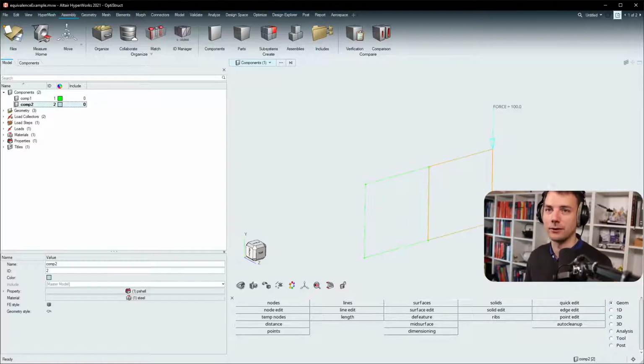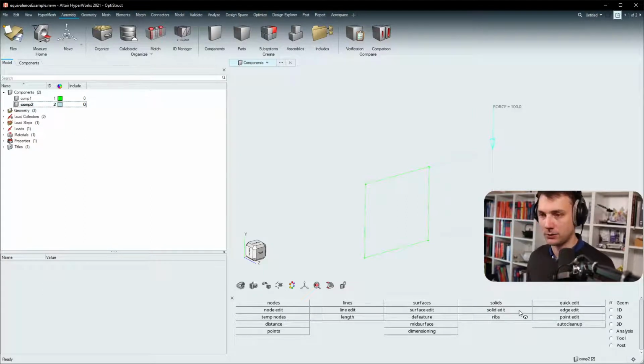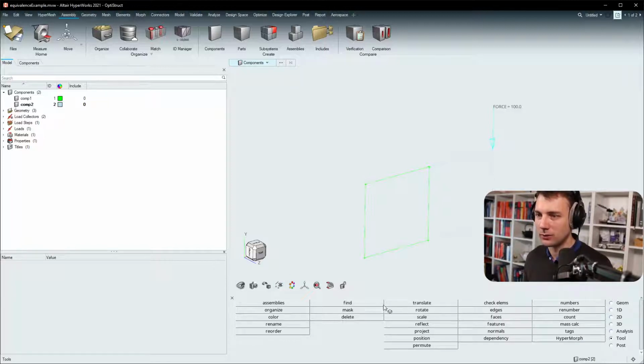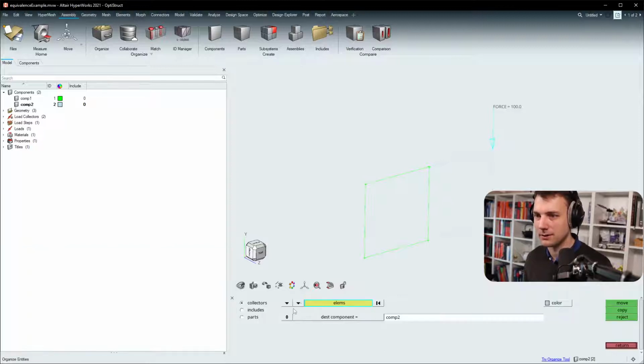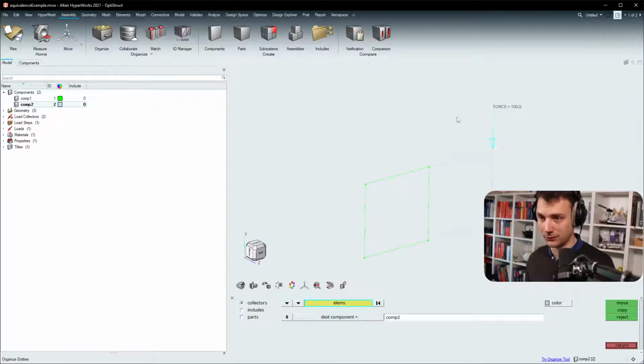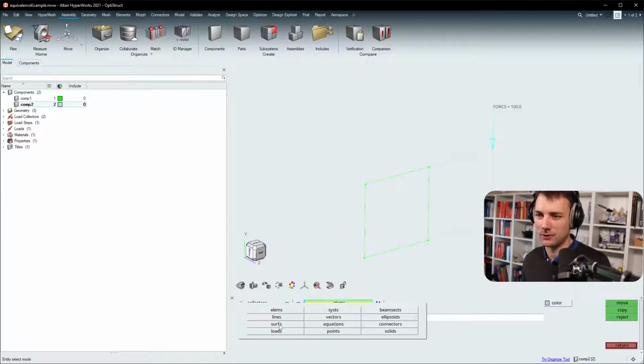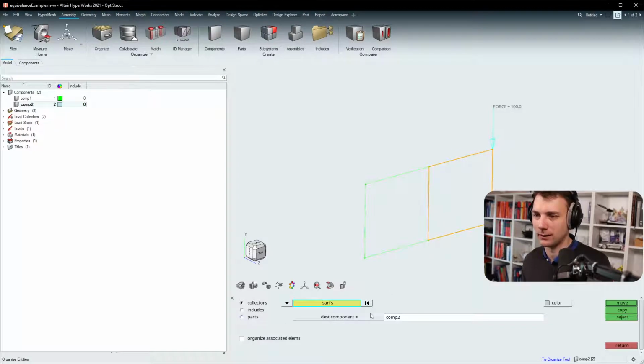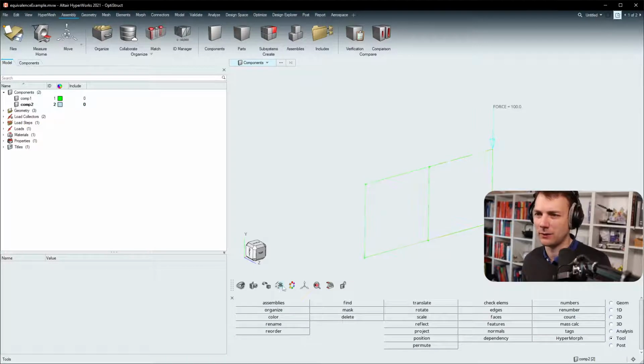Let's transfer one surface to the other component, so that those two surfaces are in the same component. I will do that with the organize panel. Yeah, it's here in tools and organize, I guess. But rather than that, Shift and F11, one of the shortcuts you should know. And now we want to shift the surface. Let's pick the right one to the component 1. Move, and we're done. So let's see if those have the same color, and choose the mesh style to be.